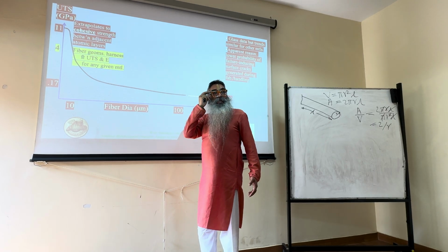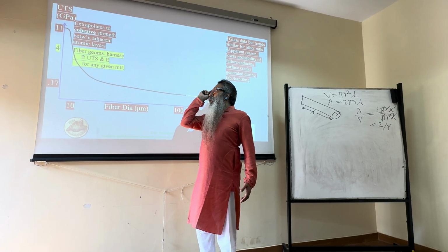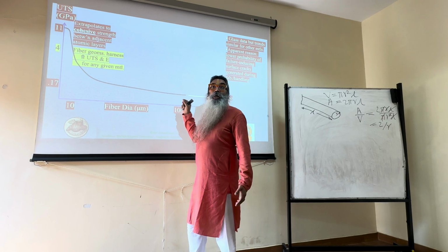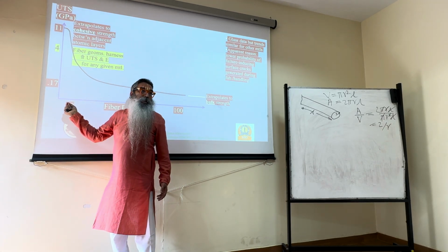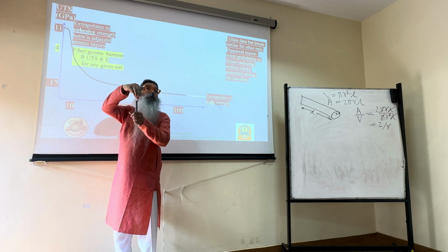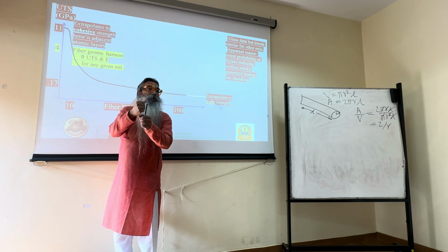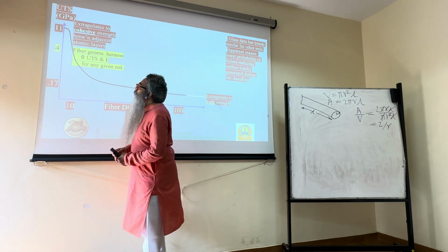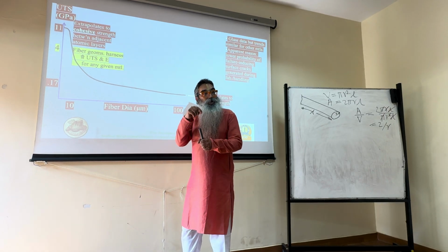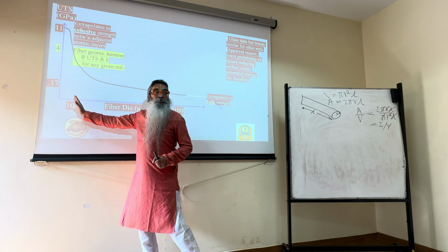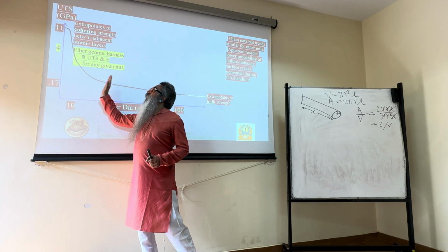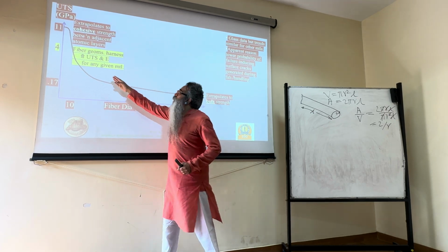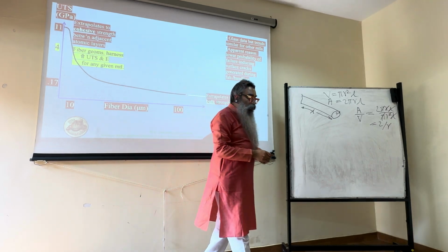So always the tendency in the materials industry is not only to go for better and better precursors, better and better manufacturing processes, but also to go for smaller and smaller diameter fibers. You might bunch a large number of small diameter fibers into a tow, which is a bunch of fibers, right? That is fine. That tow can be of any standard dimension that you typically deal with commercially. But each fiber in that tow, if it is of a smaller diameter, that's always better than fibers of larger diameter even within this range, because you see the drop is quite steep, especially close to the y-axis.